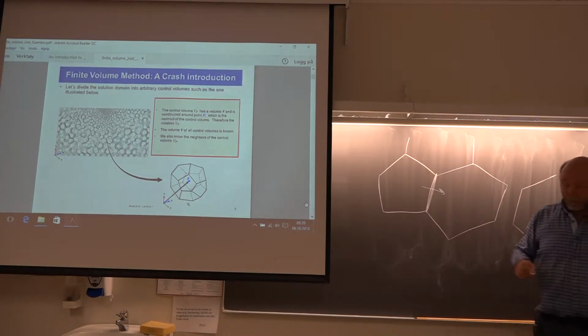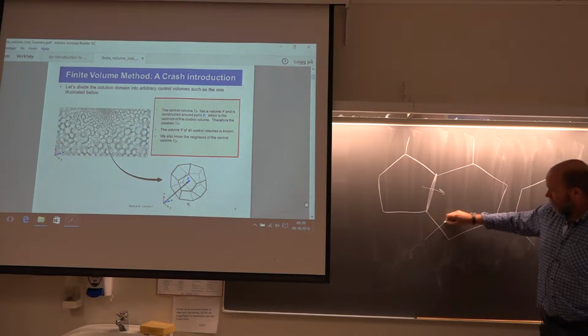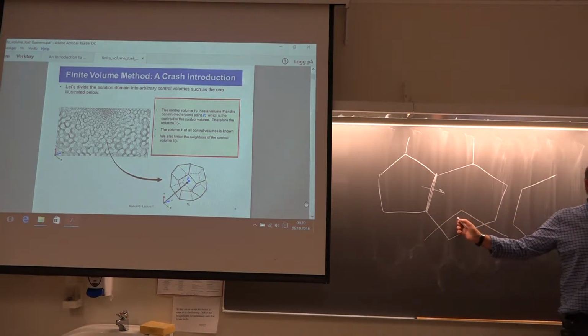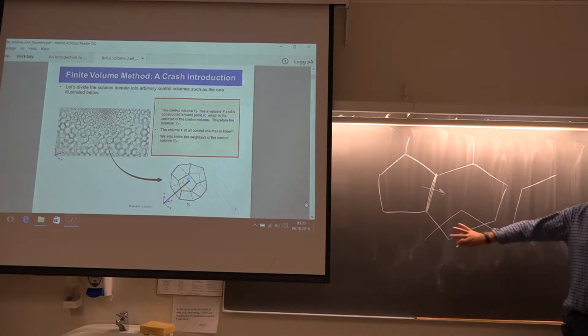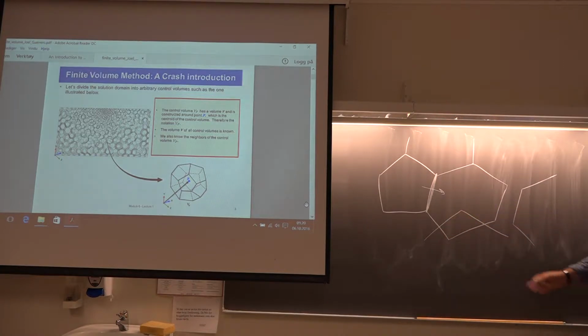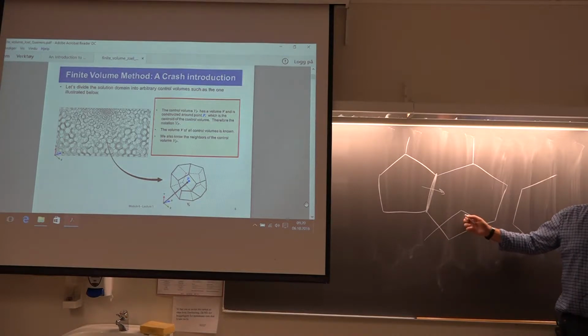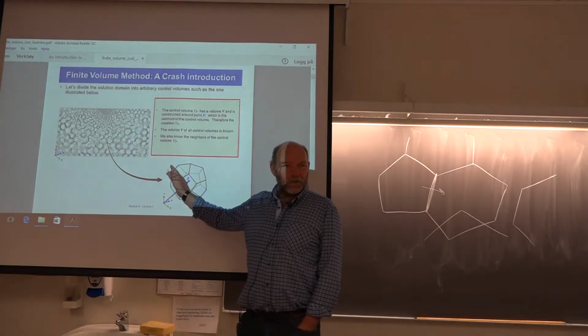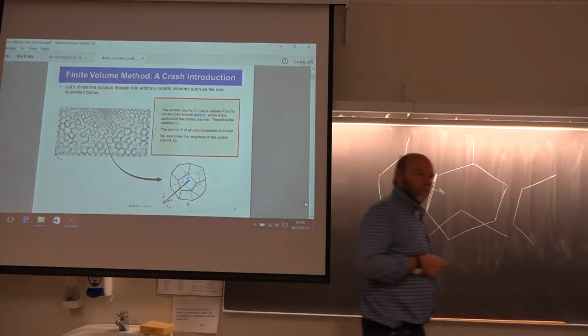What actually is common is you have a mesh coming something like this, and they overlap a little bit. That's actually happening, well, not frequently, but yes, it happens. Say you have some moving mesh, one part is standing still, the other mesh system is moving. Then we have to start interpolating here to find the values, but it can still be done. So don't limit yourself to say that they have to be face to face all the time. No, they don't have to.